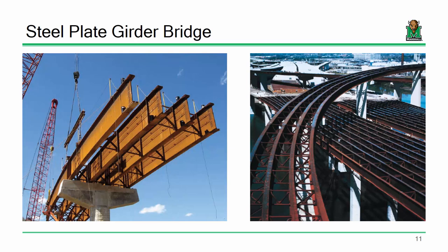And not only during construction, but if we're dealing with something like this bridge on the right, this horizontally curved flyover, those cross frames become main load-carrying components of the structure because that structure is wanting to turn over just because of its geometry. It's really wanting to twist. So those cross frames prevent that, and they can see a fair amount of force. There's also, and I don't want to get too much into detail, even just the detailing for elements like this can get really funky, because as you apply loads to these elements, obviously they're going to want to deflect.